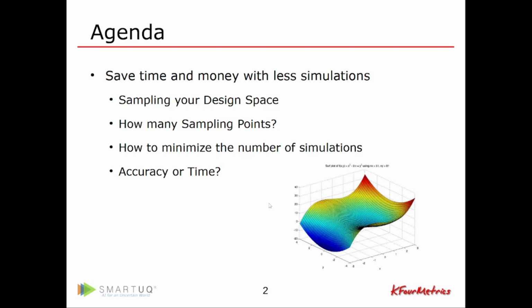So, we can easily visualize a surface in 3D space. The independent variables are the xy coordinates, the dependent variable is the z coordinate. The equation of the surface tells you the value of z for any given x and y. If we do not have an equation for the surface, we sample the surface using a coordinate measuring machine. Then we use that sample as a representation of the surface. So how do you know how many points to sample at and whether you have missed any features?